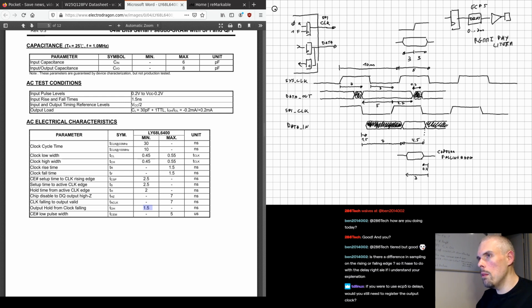But it might be variable, because I don't think the FPGA architecture itself has any dedicated path to go from the global clock network to that wire, essentially. So it would have to use normal fabric resources, like the normal routing. And the problem in the normal routing is that you have different types of routing resources. And so depending on what the router decided to use that day to route your clock, you could potentially have variable delays, which would not be good.